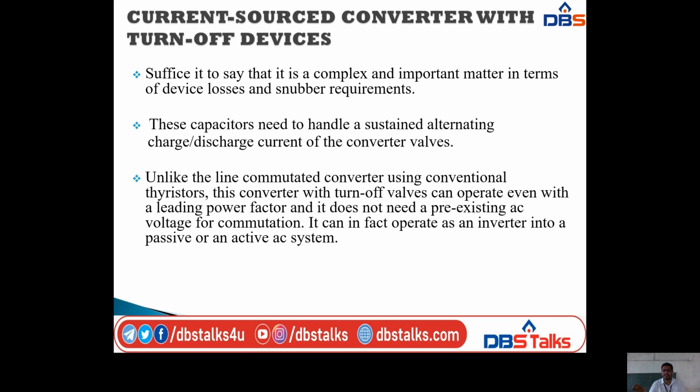Unlike the line commutated converter using conventional thyristors, this converter works with a valve leading power factor, and there is no need to take the existing AC voltage for commutation. So it can in fact operate as an inverter into a passive or an active AC system.